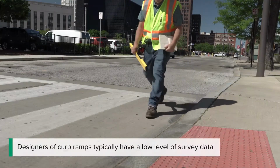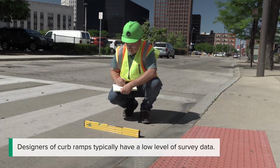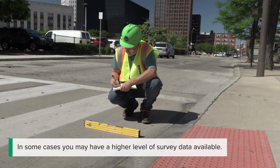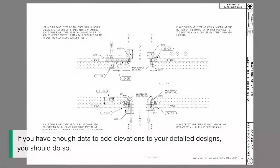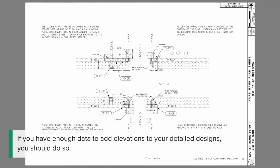Designers of curb ramps typically have a low level of survey data. The data may come from LiDAR or by gathering field measurements with a smart level. In some cases, you may have a higher level of survey data available. If you have enough data to add elevations to your detailed designs, you should do so.